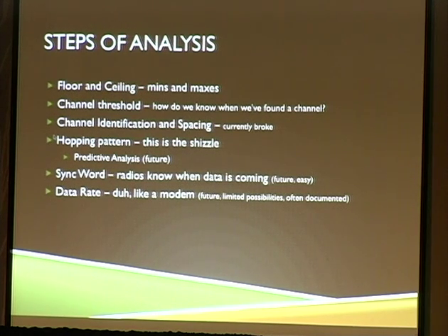The code is basically right now based on RSSI values, just watching for hops, for actual spikes in RSSI. As we get past that into predictive analysis, which I'll describe in just a minute, it will also determine a sync word for most of the channels that you've identified. So it'll guess at some channels based on the RSSI values in the first phase. It'll then sit and listen on a channel, and when information comes in, it will have specific hacked values in the registers of the RF controller that say, hand everything in and we'll analyze from here.